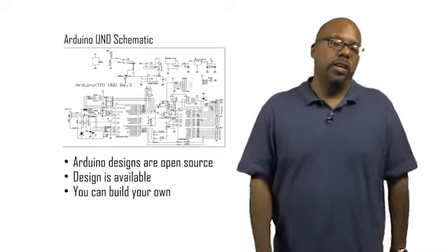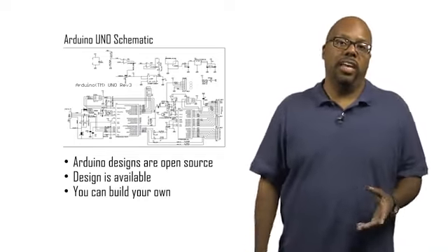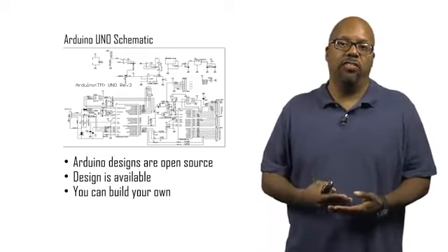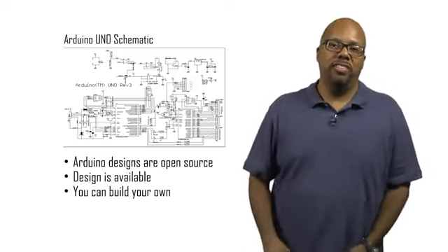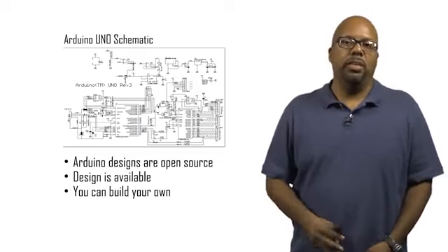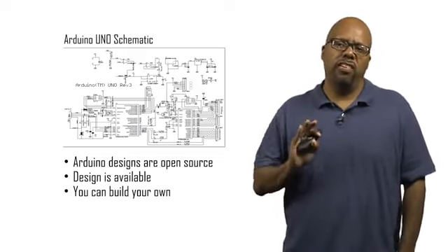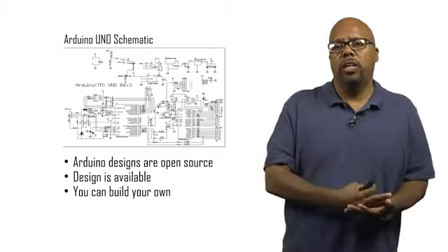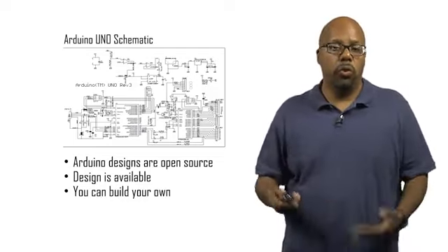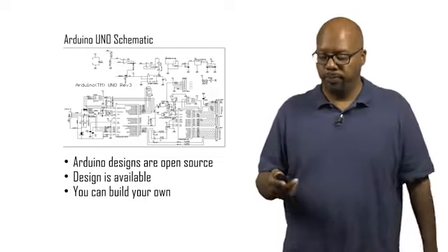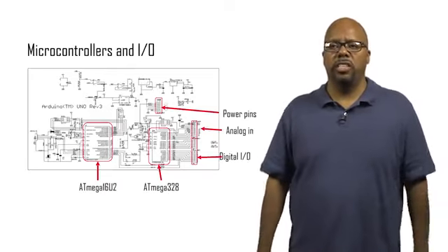So it's laid out in a completely different fashion in the schematic than it actually is on the physical board. Now, if you want to see the actual board layout, the Eagle files, the CAD files for that, are available on arduino.cc, and they are harder to read, but you can look at that. This is just a wiring schematic that shows you what components should be connected to what, and what pins should be connected to what pins. So let's look at it in a little more detail.